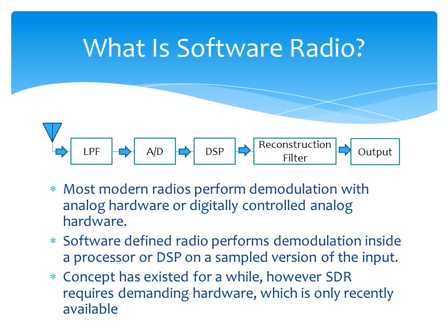The software-defined radio concept is essentially a radio that is demodulated on computer hardware as opposed to traditional analog hardware. You see here we have a basic flow diagram. You'd simply take the input, perform a low-pass filter on it, convert it to a digital signal using an A-to-D converter. You perform your DSP processing, which is where the demodulation is actually done, and then you convert it to output.